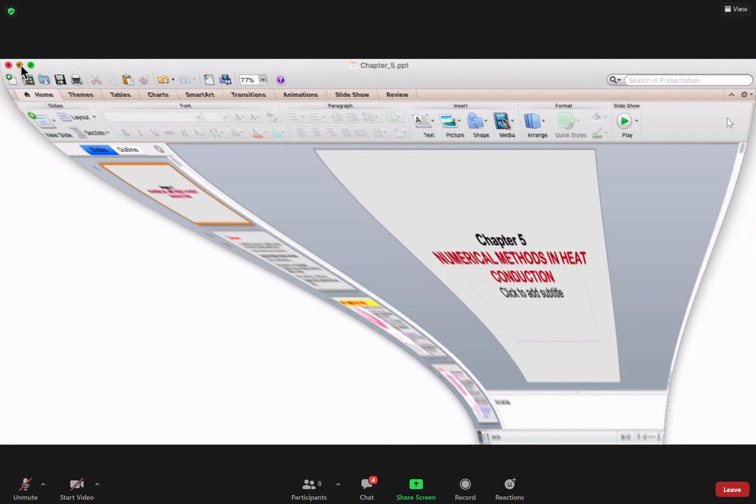So do we use the equation when the Fourier number is lower than 0.2? Then you have to sit down and do a lot of work, my friend, because the sum here, as you can see, is from 1 to infinity. Therefore, you have to solve for the eigenvalues lambda 1, lambda 2, lambda 3, lambda 4, lambda 5, and so on. Rather than you doing it, somebody has done it and came out with this graph. Therefore, you do not need to solve it. You can use this figure that you have here. This figure is the solution to this equation.